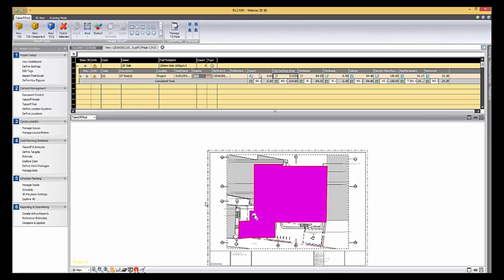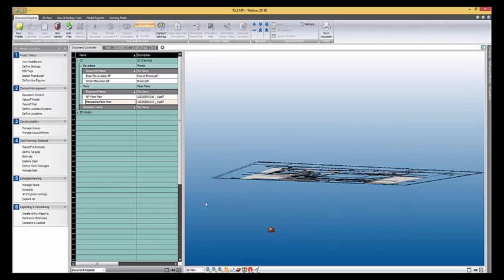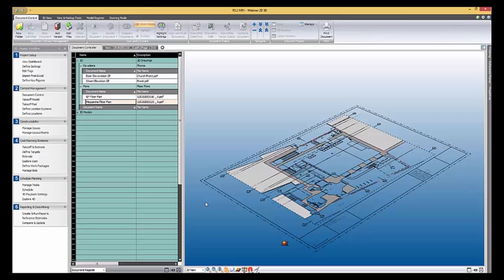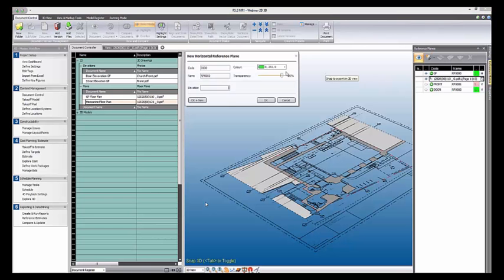So the next thing we're going to look at, we've done a bit of a takeoff, is, for those of you who saw the screenshot, mapping those 2D drawings in a 3D space. The reason for doing this is it helps give people a bit of context. So there's that 2D drawing. Just spin it around. And what I'm going to do is take the mezzanine floor and map it at an elevated plane hovering above this ground floor. So first of all, make the plane, and I'm going to put it at 11 meters elevation.